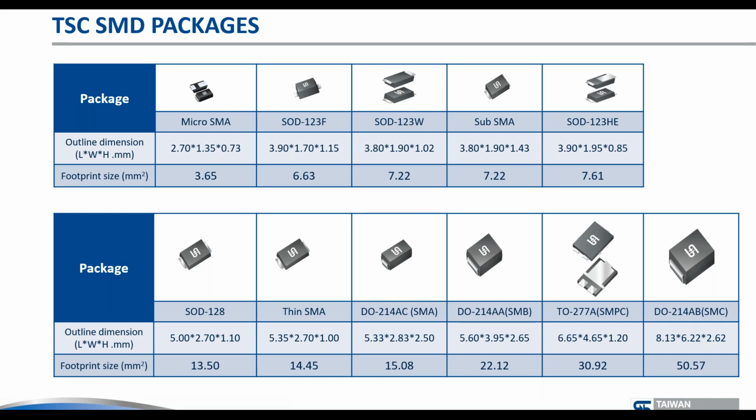When you see the footprint size, there are various ways of defining that. We define it by multiplying the length with the width. But obviously, if you include the protruding tabs and the minimum recommended solder pads, the SOD128 is pretty much similar to the others.